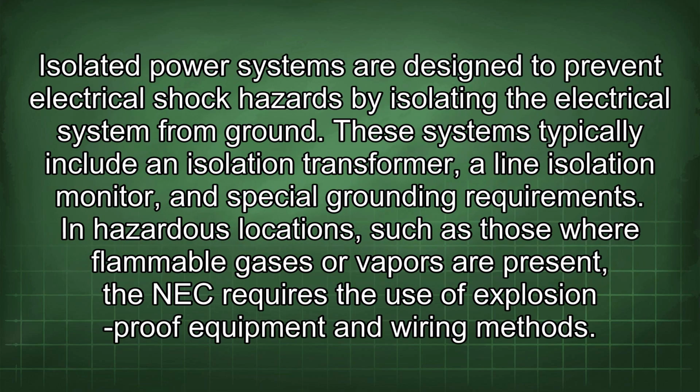Isolated power systems are designed to prevent electrical shock hazards by isolating the electrical system from ground. These systems typically include an isolation transformer, a line isolation monitor, and special grounding requirements.